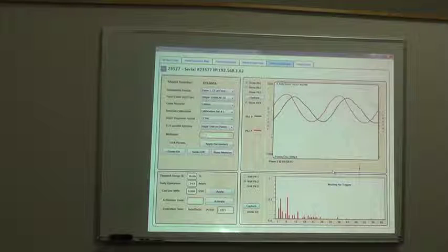So it says basically waiting for trigger. One other thing that I'm going to do, when it's waiting, I'm going to clear the display, because I understand that that is a bit of a headache. Because there are multiple phases, if you're only updating phase 1, but you already have the data for phase 2 and 3, then you're really comparing phase 2 from now to phase 3 from before. And that's a no-no. So that's a mistake. So what I'm going to do is when you say capture, erase the display, so only what you captured comes up. And if it doesn't work, do it again, because you may miss it, because it has a very low priority. So you might have to press that a couple of times, but eventually you will capture it.